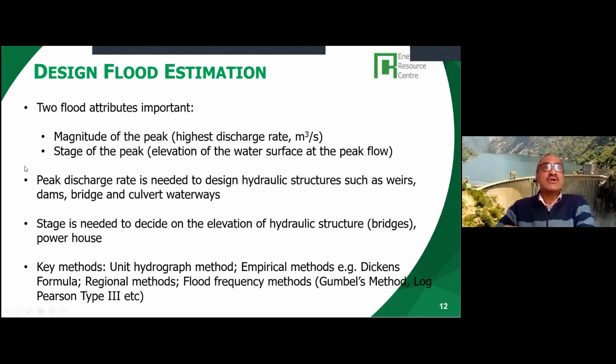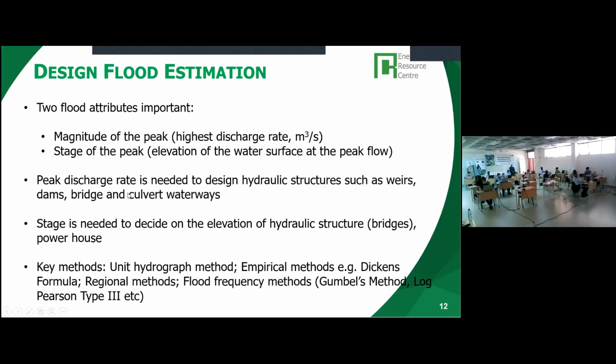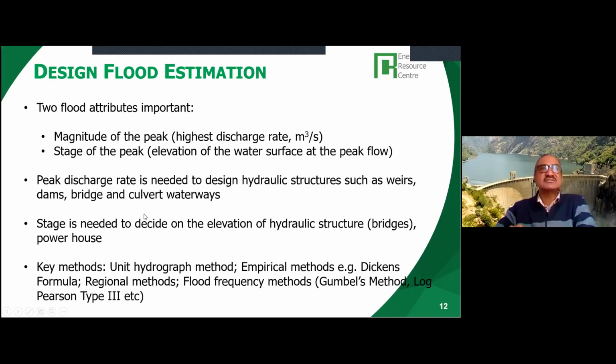Okay, so why do we need this design flood? We need this design flood to design hydraulic structures such as weirs, dams, bridges, culverts, waterways, etc. And why do you need the elevation, the stage, the water level? Because we want to decide on the elevation of the hydraulic structures like bridges or powerhouse.